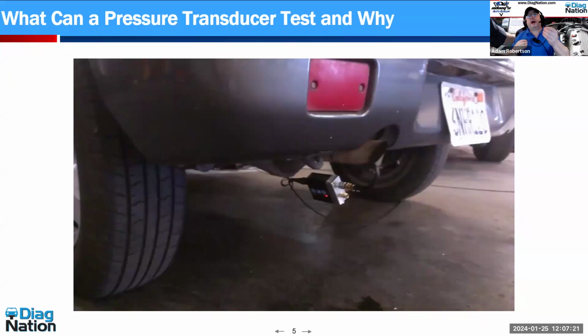One of the ways I describe this action is, if you think about the four cycles of an engine, when that piston comes up on the compression stroke and compresses our mixture, when it fires, it's the expanding gas that shoves that piston down. And as that piston is going down, that expanded gas creeps out the exhaust valve. When that exhaust valve opens to let it out, there's a burst, or a volume, of expanded gas that goes into the tailpipe.